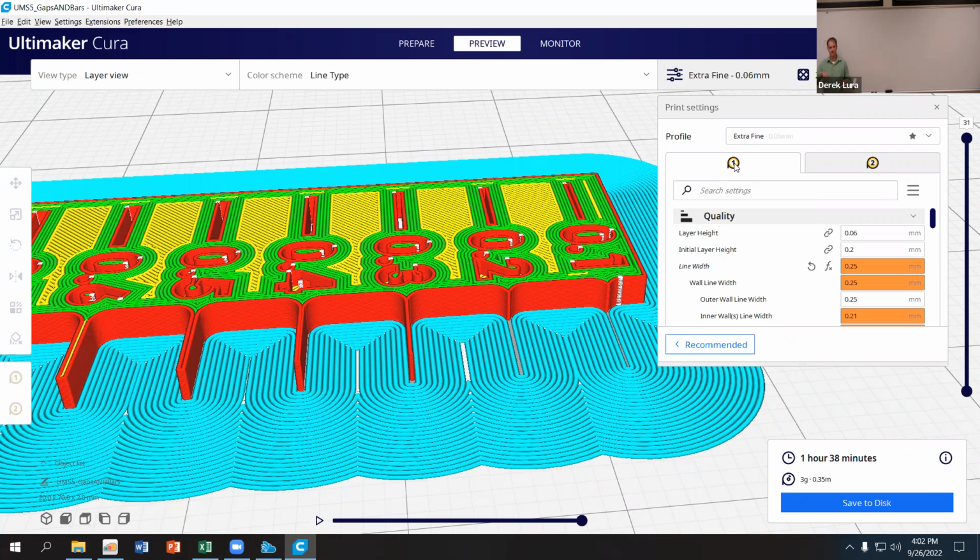It also has a very plastic transition. So it has a range of temperatures where it goes from being solid to squishy to squishier to fluid, as opposed to going from solid to fluid at a single temperature. And so it's less susceptible to small variations in temperature as you're changing because the viscosity is less temperature dependent, right, than some of the other plastics.